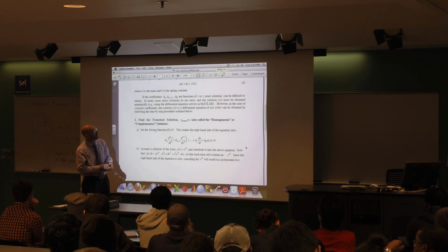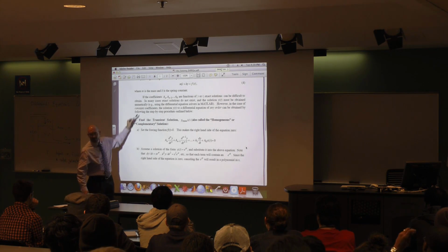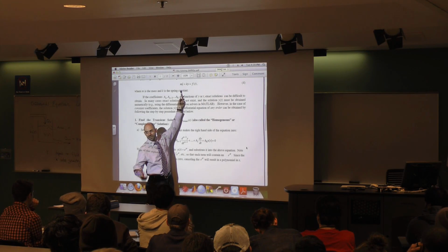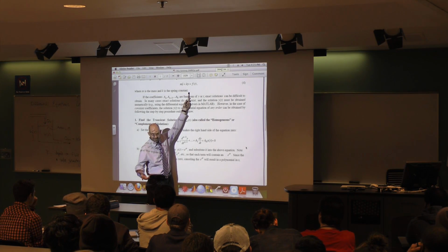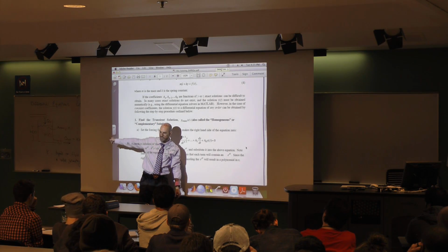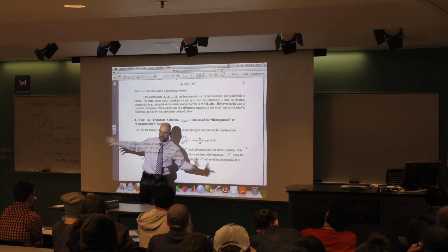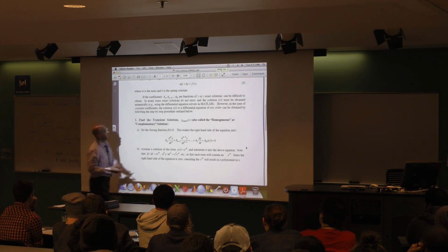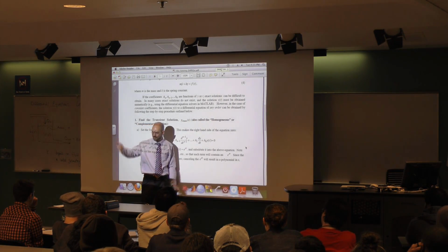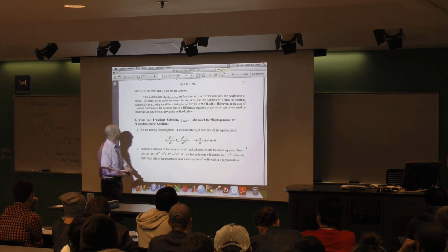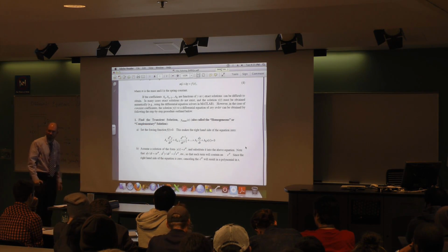If the coefficients are constants, like in a spring mass, m is the mass, it's a constant. K is the spring stiffness, it's a constant. In our problem here, I've got K, which is for the fluid in the valve. I've got A, which is the area. These are constants. If that is true, then the solution to a differential equation of any order, first order, second order, third order, no matter how many derivatives, is all the procedure outlined on this page.